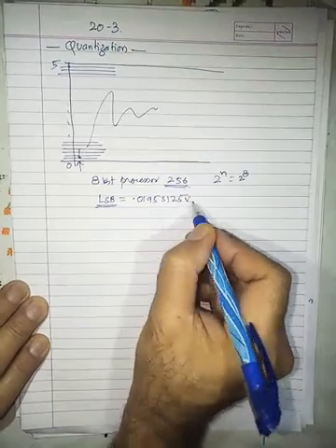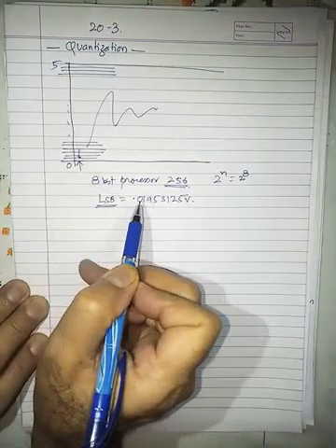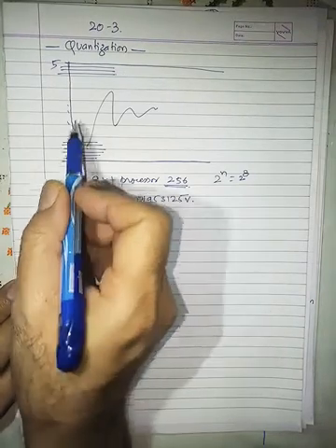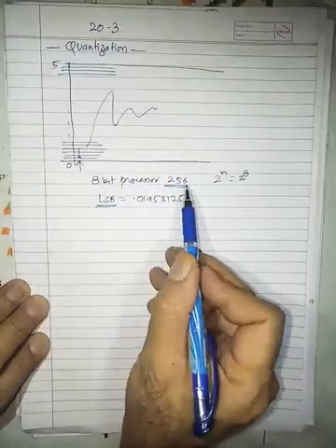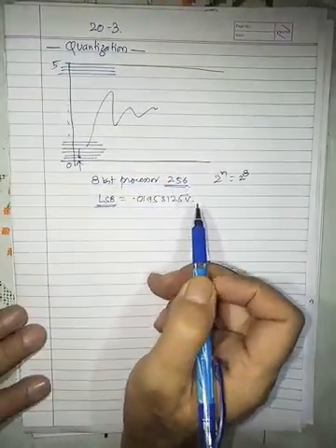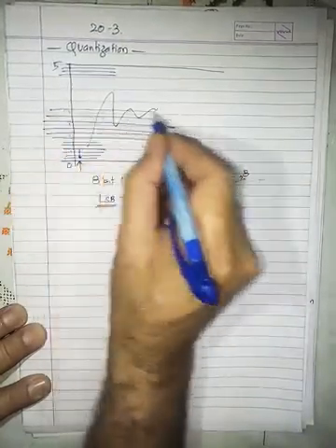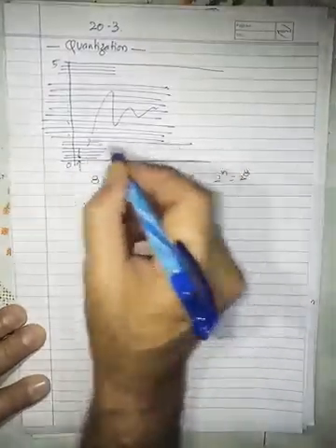0.019532125 volts. So that way the next level will be 0.01 plus 0.01, and that way this will go on increasing. Ultimately this will reach 5 volts after adding 256 times. Now let us say I have these 256 levels in this, and let us say